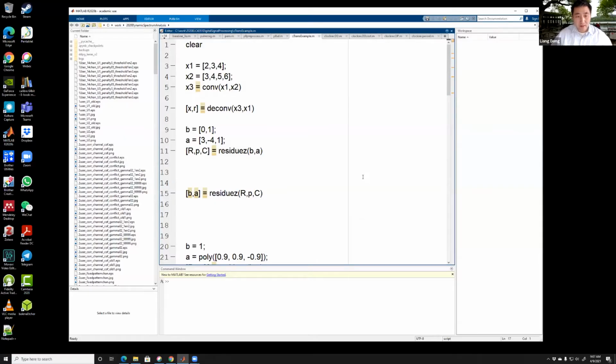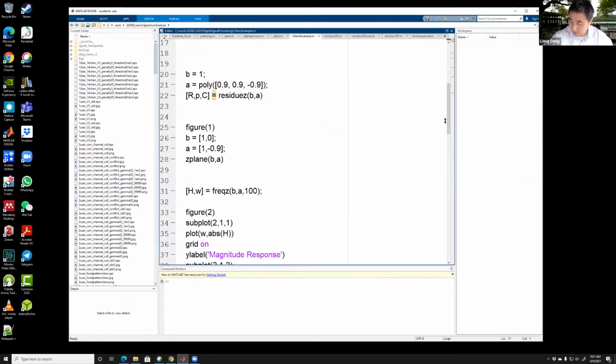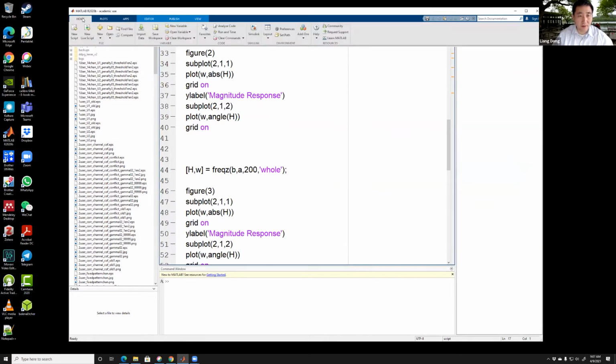So we're looking at the MATLAB example. Let me go back to that. And then I'm going to give some other practical examples of practical devices, the digital resonator, the digital comb, from the book. So we are using this example from last time to look into how to place poles and zeros to do a filtering design. We have here placed the poles to generate a filter that amplifies signal components.